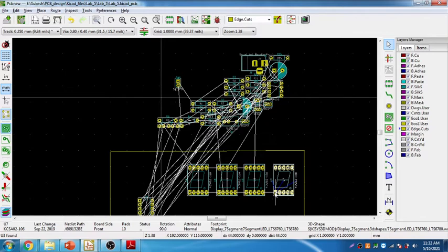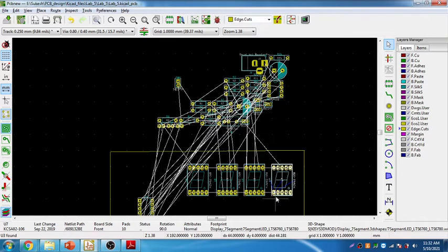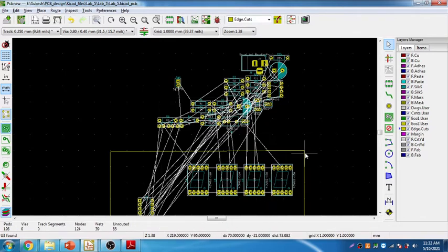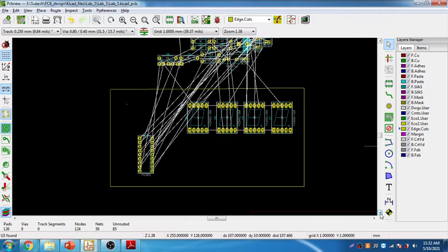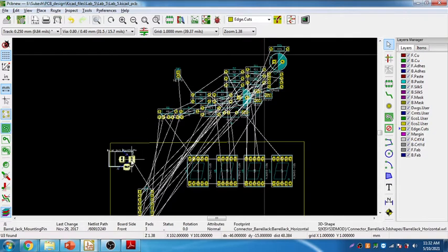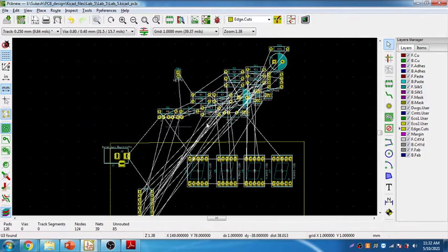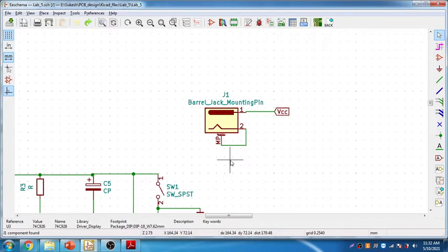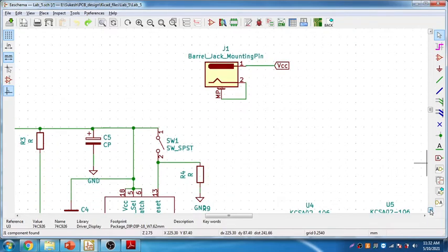Okay, fine. So as far as possible, maintain equidistance between these, because that is a physical display which is going to be put up on the top of the board, and let it be well aligned. And this is the power, put it over here, and the capacitors, resistors are there. So we need to carefully choose those items one by one. Just look at the pin number where they are from.